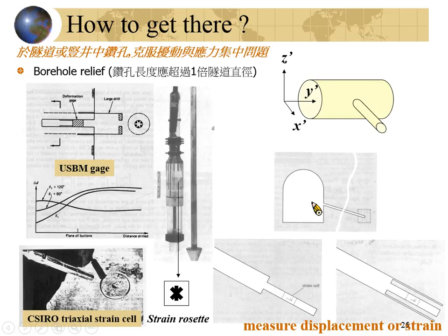Hydraulic fracturing is easy to operate. You only need to inject water into a borehole. But for this kind of measurement, a lot of precise work needs to be carefully conducted. So for a borehole of 10 meters, I think it will be okay. But 100 meters will be difficult, and 1 kilometer will be almost impossible.